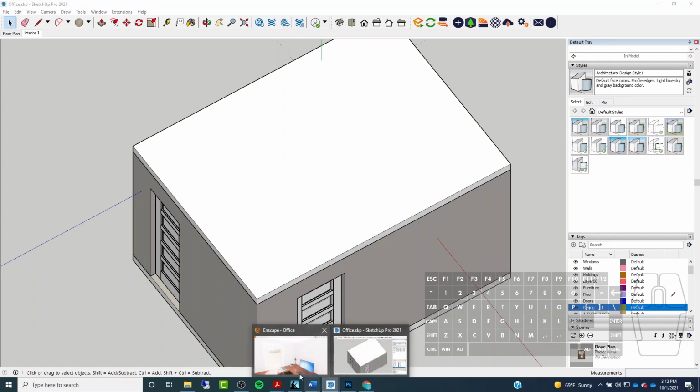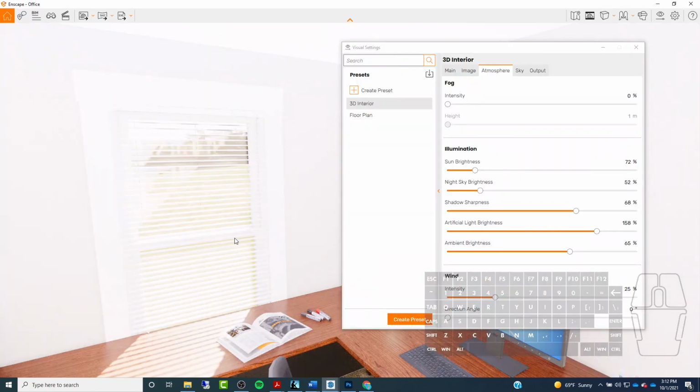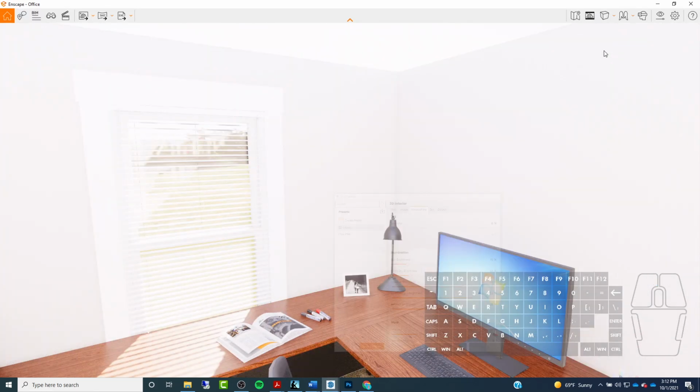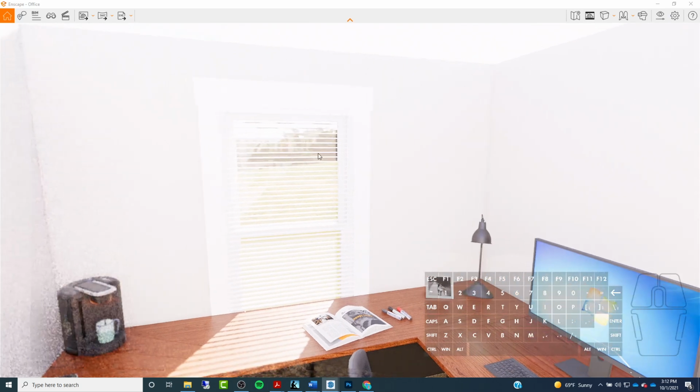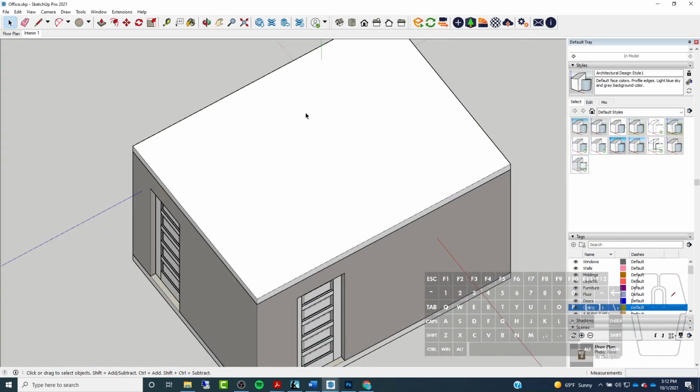So whenever I have to turn off the ceiling, it makes things harder, because if I'm working over here inside an Enscape view, when I turn off the ceiling, it's acting like there's no ceiling and it's making the scene way too bright and I can't actually see what the lighting is doing. So the way around that is to use a little something called section planes. Section planes are a really important tool, and they're also used for setting up really cool views, which I'll show you as well. Like cool 3D perspective views.